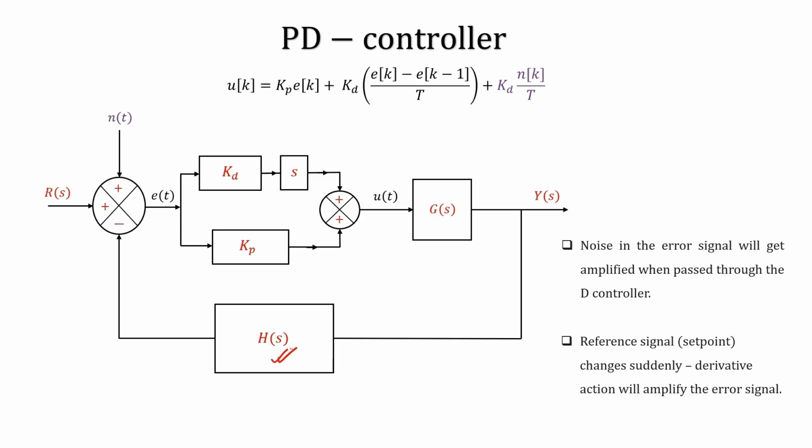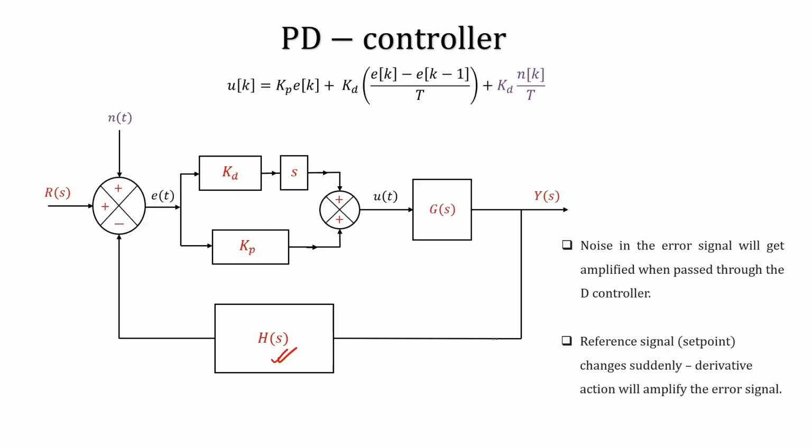When you are using sensors there will always be some noise, okay, that noise will always corrupt the actual signal. Now, let us think of that noise as an additive noise. Basically the actual signal here is HSYS, okay, but plus with that some noise is coming in. So, this noise I am taking out separately as n of t, okay, in time domain n of t, in Laplace domain n of s. Now, look at this and think about this system.